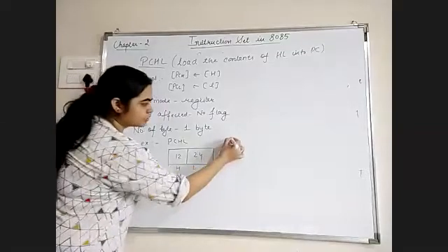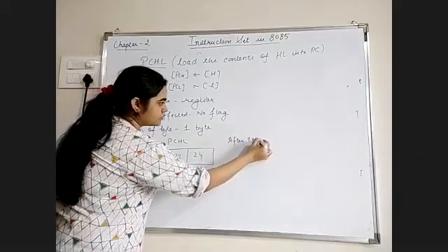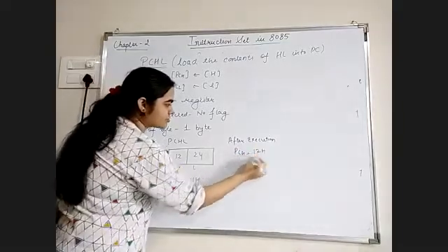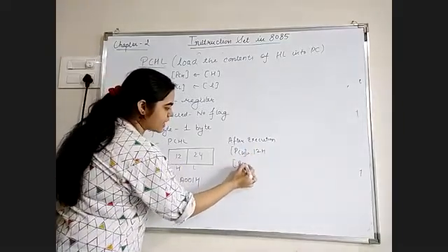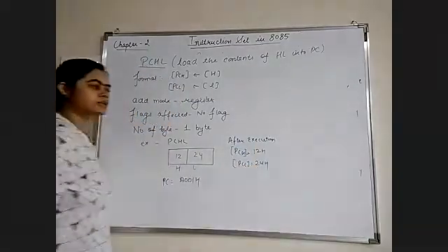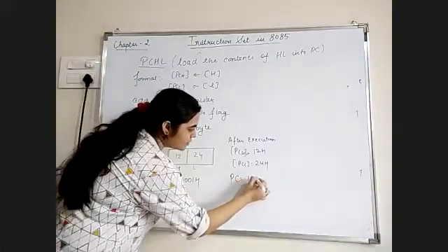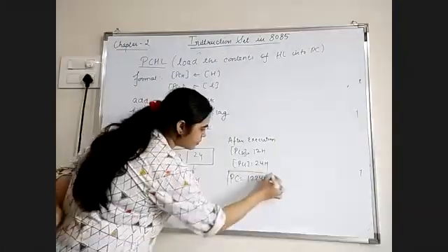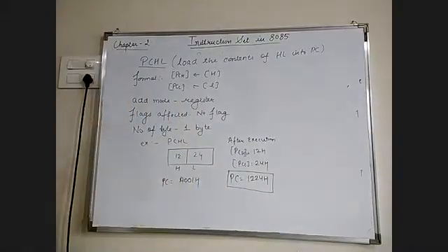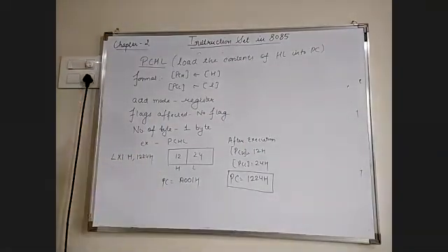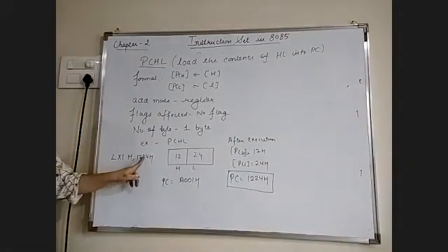So after execution, PCH is having value 12H and PCL is having value 24H. So these are the values after the execution. So if we write it as PC, then the new value of the program counter will be 1224H. Okay, so this is how this instruction will work. Means we are loading the HL pair with the value 1224H first. So this instruction will load the HL pair with 1224H.